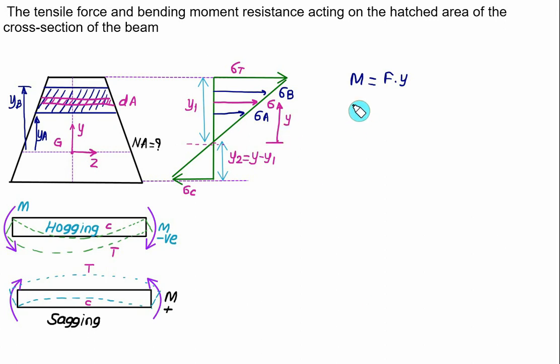So the first formula you have to use is that the maximum stress sigma t is at a distance equal to y1, and for the given elemental area we have a stress equal to sigma, which is located at a distance y from the neutral axis. Now we can calculate the value of sigma as sigma t divided by y1 multiplied by the distance y.